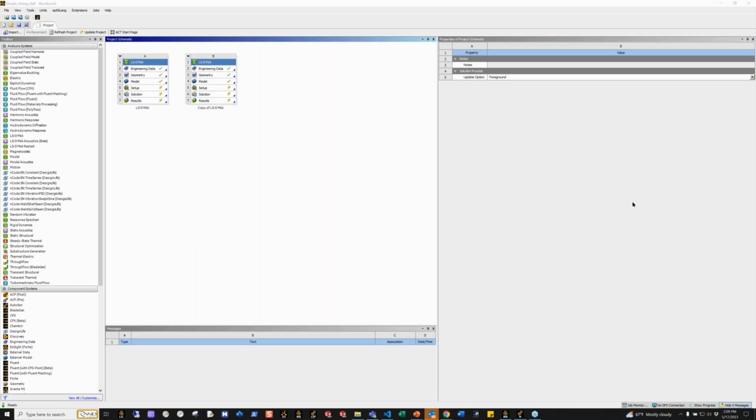Yeah. Perfect. Let's see here. Okay, this one's really good. Why would I use Ansys LS-DYNA over Mechanical? So remember, when you or your organization have simulation capability, Ansys Mechanical is mostly, or I should say entirely, an implicit code.